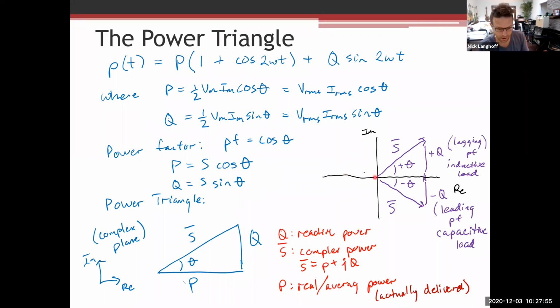The real power would be a negative power, and that's in fact associated with a negative resistance that actually gives power back to the system instead of absorbing it from the system, like a speaker, right? An 8-ohm speaker takes electrical energy from an amplifier and turns it into sound, but the energy is lost from the electrical system and transferred to the acoustical system, right?